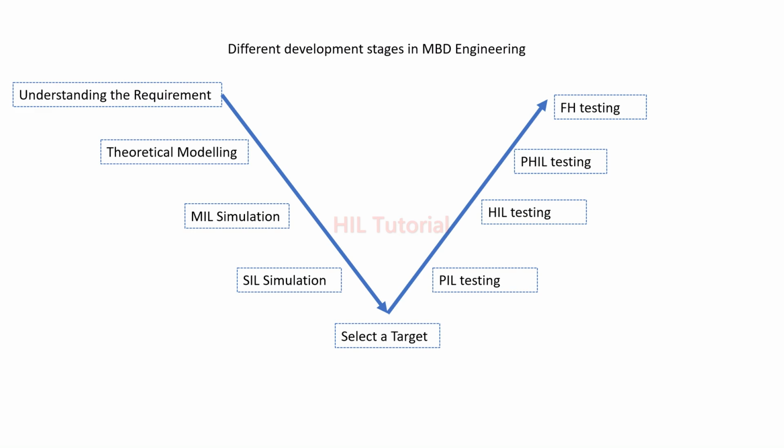Then easily you can have a physical inverter, motor and all these things, and just deploy your microcontroller with the physical inverter and motor, and easily you can start full hardware testing. Once full hardware testing is over, then you are assured that your developed model is ready for mass production. That means it is ready for delivering to the customer.